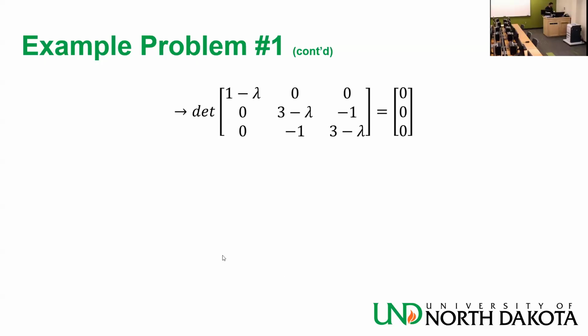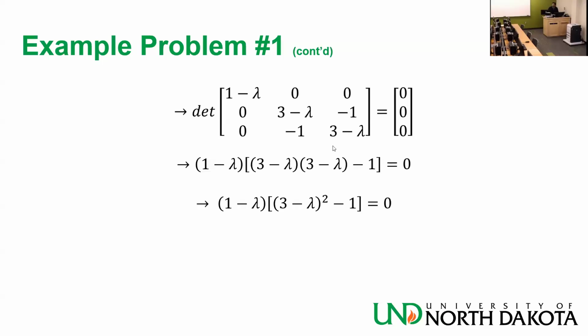So we do it, we end up with an algebraic equation and we solve for lambda. Now lambda will have 3 values. Why will it have 3 values? Because there are 3 stresses, right? 3 stresses mutually orthogonal. So 3 values of lambda: lambda 1, lambda 2, lambda 3. In this case, lambda equals 1, 2, and 4. Okay, so lambda 1 will be 4, because that's the most compressive. Lambda 2 would be 2, and lambda 3 would be 1. Okay, easy. Nothing terrible.